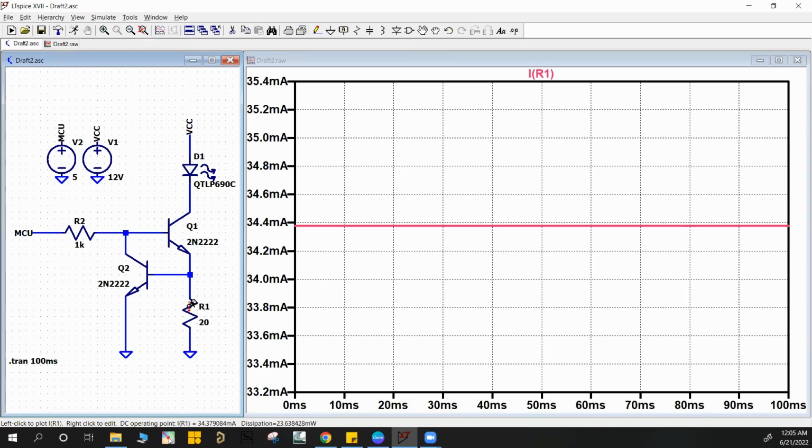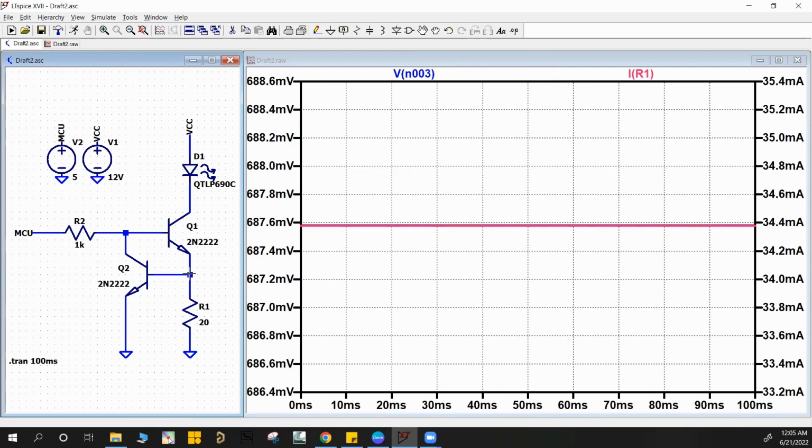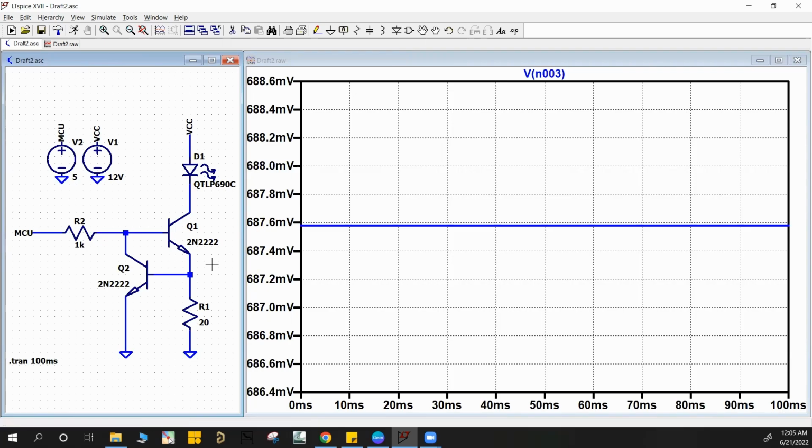The other thing is you could hover outside this resistor, right over here where the little lighter blue line is. This is just a wire. For wires, what LTspice allows you to do is plot voltage. So this red pin is a voltage probe. This guy that looks like a fly or something is a current probe, and this guy is a voltage probe. If you press it, it shows you the voltage. The voltage here, as we calculated, was about 0.6 volts, at 0.67 volts in this case.